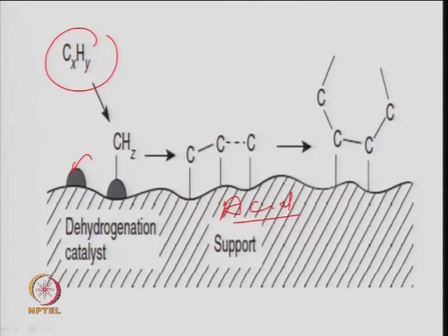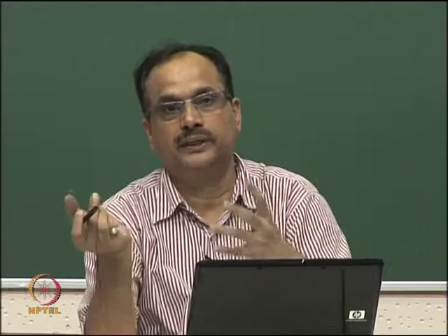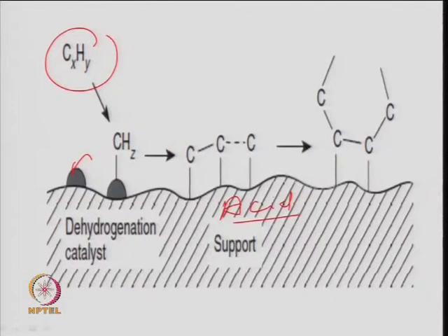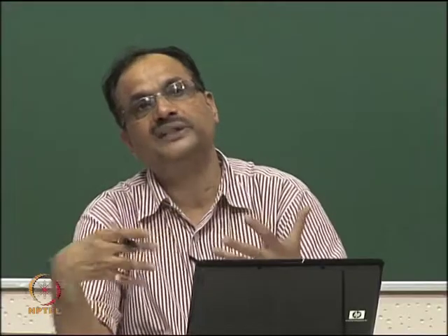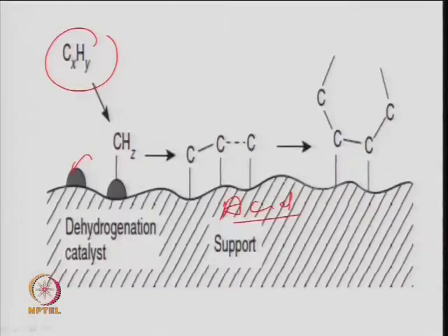And finally, if you look at here, that makes a dehydroaromatization type reaction. So, further hydrogen is removed and it starts to form a ring compound, cyclic compounds. So, then more and more hydrogen is removed and finally, it gets a polycyclic aromatic hydrocarbon. So, that is your coke carbon precursor. So, finally, this will result in a coke formation. It is completely nothing but a polycyclic aromatic hydrocarbon, condensed polyaromatic hydrocarbon.